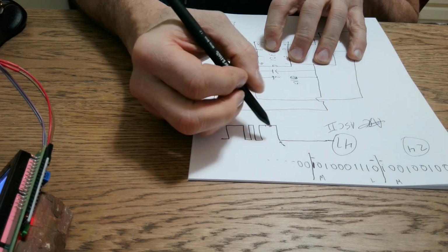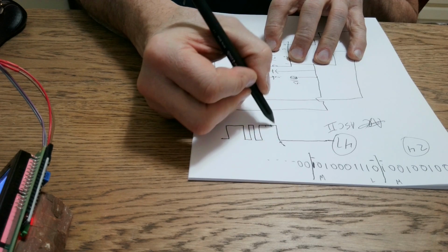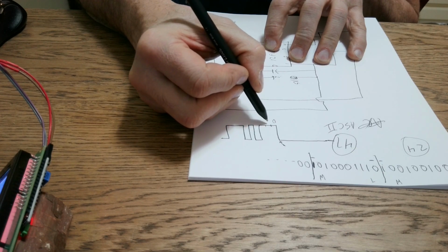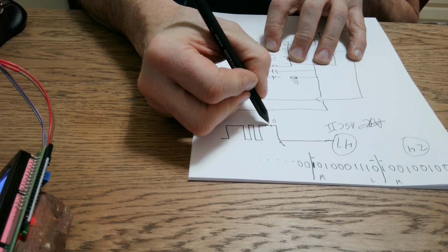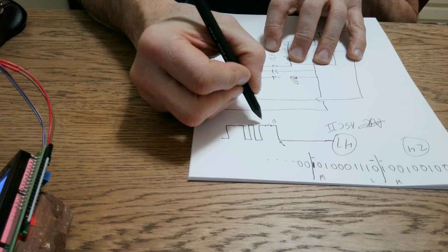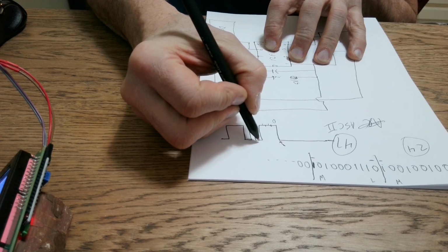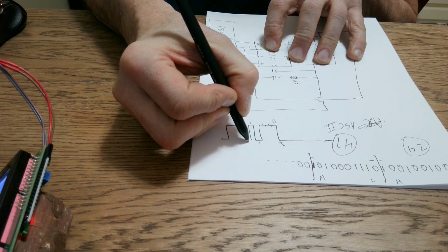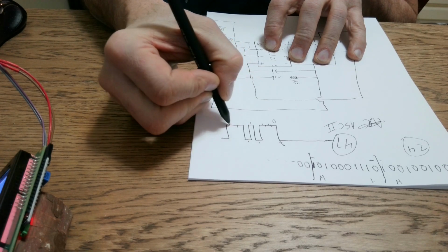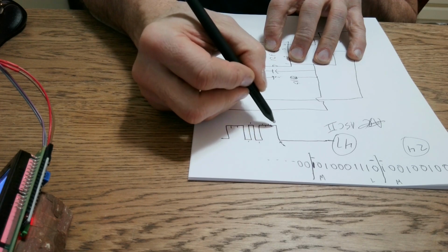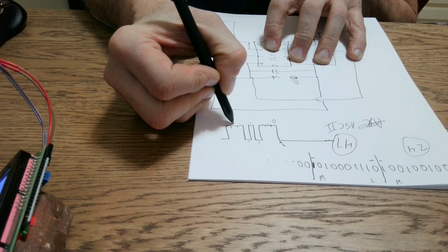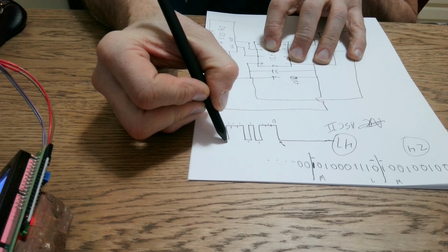If I see a low, I know that right after the low comes the start bit. And then after that will be the real stuff, like the data that I want. I want to actually read the data right in the dead center of it, right in the middle, because that's where I'm guaranteed to have the most accurate value for that bit of data, right? So I'm going to try and read every 100 microseconds in order to grab the middle of a piece of data.